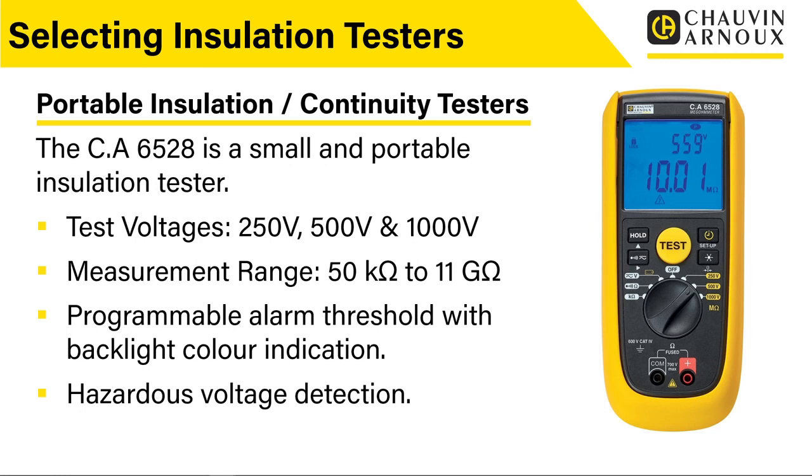It's also quite useful if you're testing a piece of equipment. Maybe you're leaving it connected up to the instrument and you're doing some alterations, or you're wiggling some cables or something like that in a piece of equipment, and then you'll get that indication. So the alarm function is quite good on that. You've also got the hazardous voltage detection built in. So if you connect this up to an equipment and the circuit or equipment you've connected up to is still live, again, it will warn you of that, and it won't let you actually carry out the test while that dangerous voltage is there. So again, that's a great safety feature built into this.